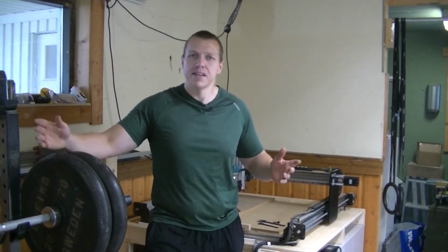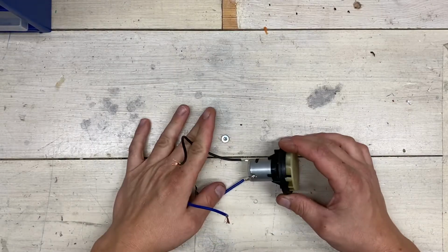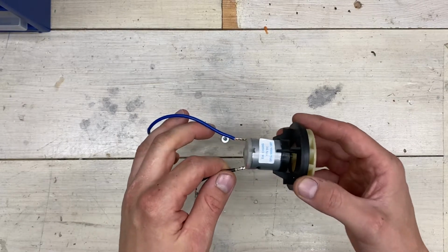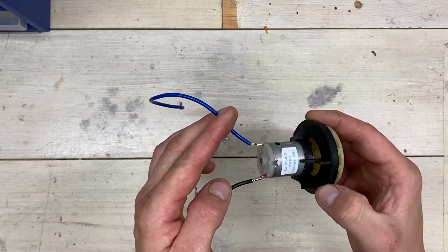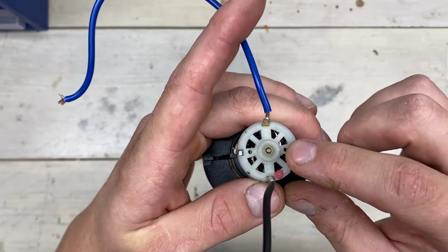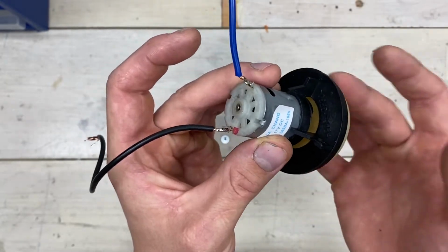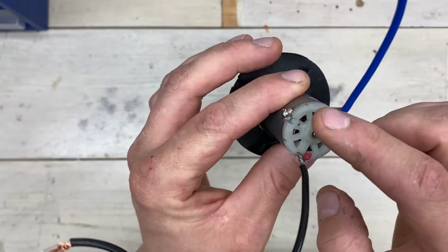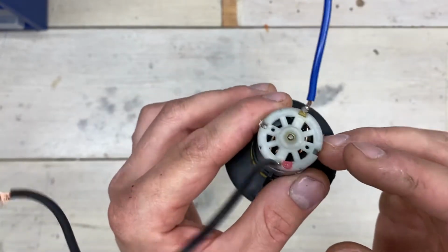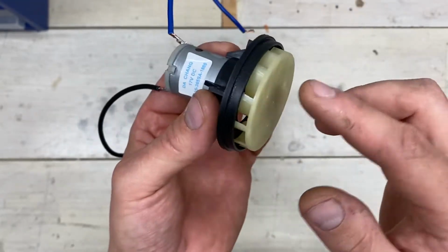Let's start with the most basic and then move up from there. This is probably the most basic motor there is. This is a small permanent magnet brushed DC motor. And they're called brushed because here you can see they have two carbon brushes. And this is to turn the rotor, the part inside the motor that rotates, into an electromagnet. On the outside ring of this motor are two or more permanent magnets. And the magnetic field of the rotor is reverse polarity compared to the permanent magnets, and this is what imparts the motion.